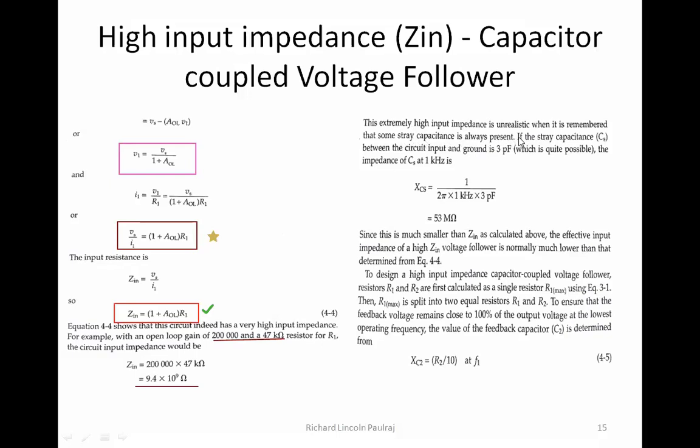Always keep in mind that wherever there are junctions, like the junction between resistances R1 and R2, there is going to be a stray capacitance. So at every junction there is a capacitance, which we usually refer to as parasitic capacitance. The engineer has not designed it, like how we have designed C1, C2, and C3, but it comes up on its own. So these are called stray capacitances.